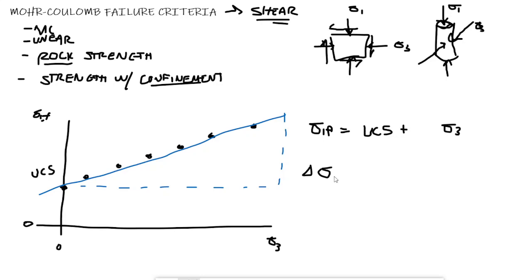We won't write the subtractions out. We'll say delta sigma 1f over delta sigma 3, which will just be the final sigma 3 you calculate minus 0. And we call that property beta, right? So thinking about it on that graph, that's going to be your little triangle, your little slope, that's going to be beta. And beta is the strengthening parameter. So we put that in there.